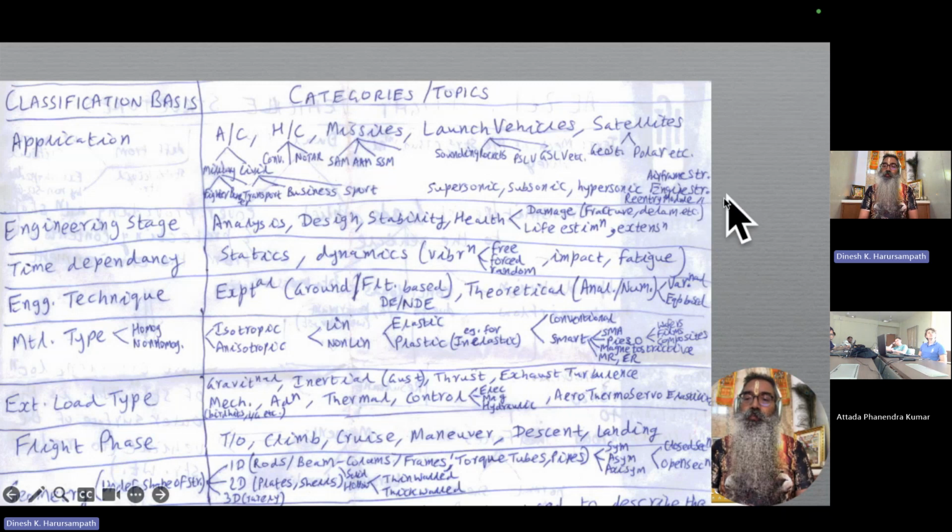Next, we talk of the speeds at which any of these might be flying, especially in case of aircraft. You could have low subsonic flights, whereas most others are flying at high speeds, and Mach numbers which are closer to 1 transonic, greater than 1 supersonic, and much greater than 1, around 5 or more, hypersonic kind of aircraft. And each of them has its own nuances.